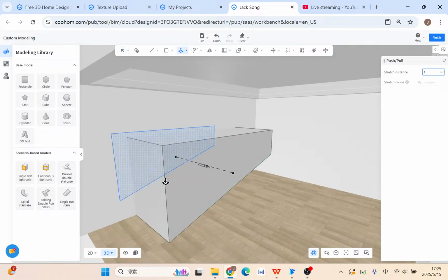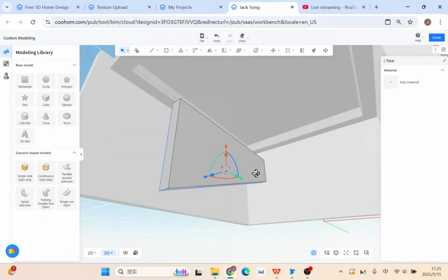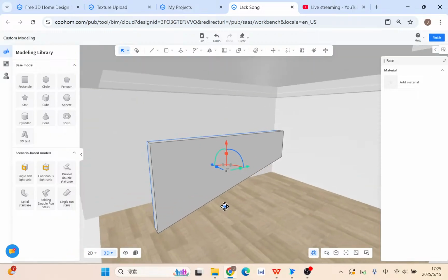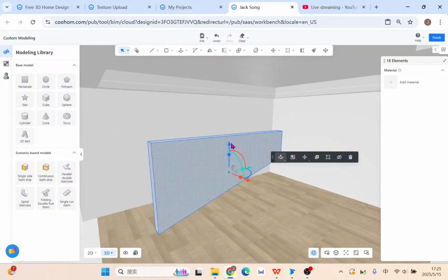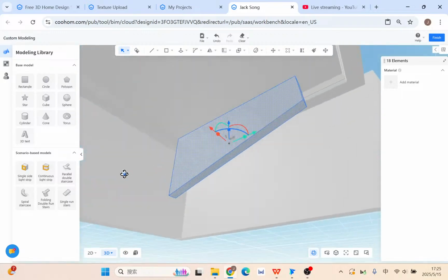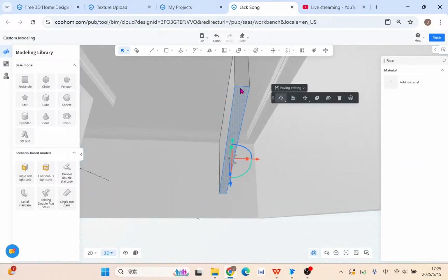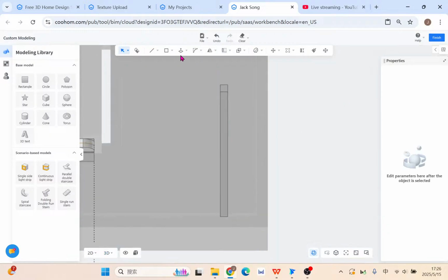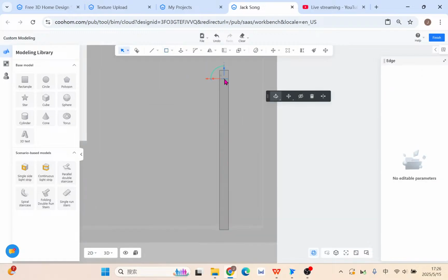This time 200, make it thicker, just in order to let you know. Okay, holding down Shift button. You see here, you can use the paving edit, or I suggest we directly use 2D. Yeah, draw the boundary, click, split into three parts.